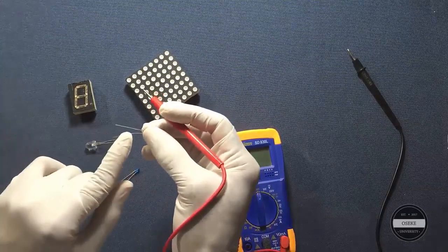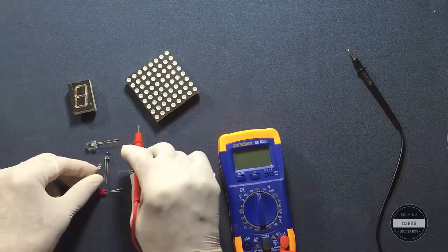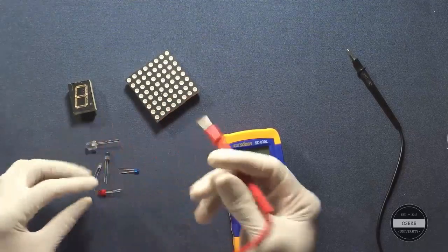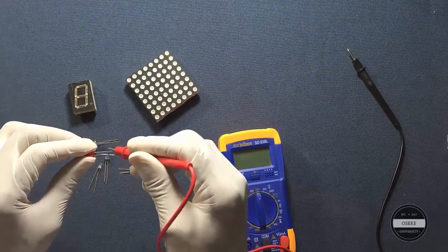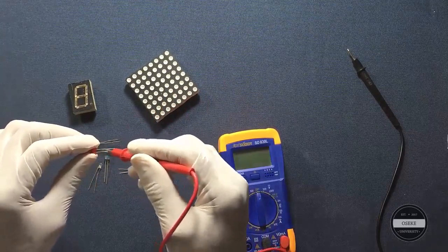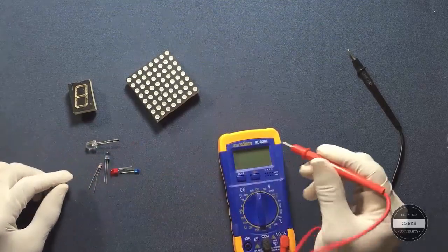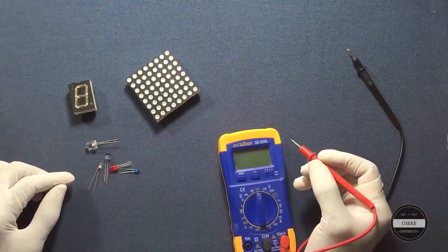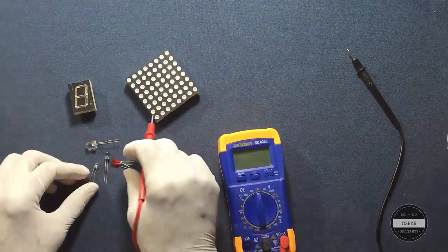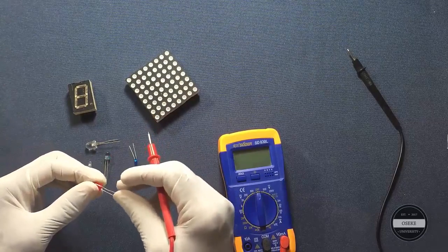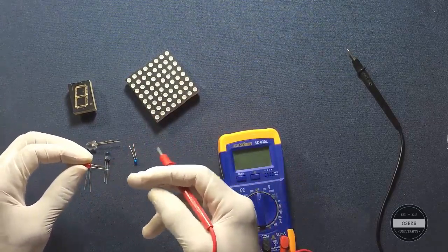And the same thing applies here. Longer one, shorter one. So these ones are easy to decipher. I've seen LEDs where the longer lead is negative. Probably that was an error, but I've seen one like that, only once anyway. So that is how they look, and now you know how to tell their positive and negative lead.